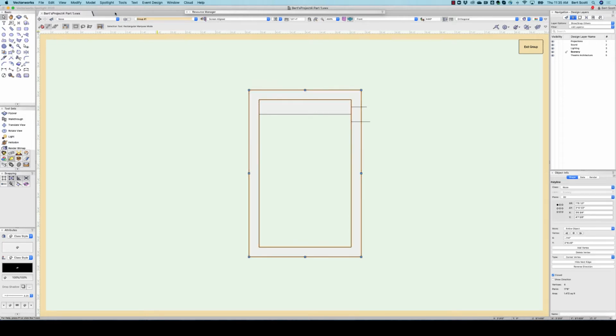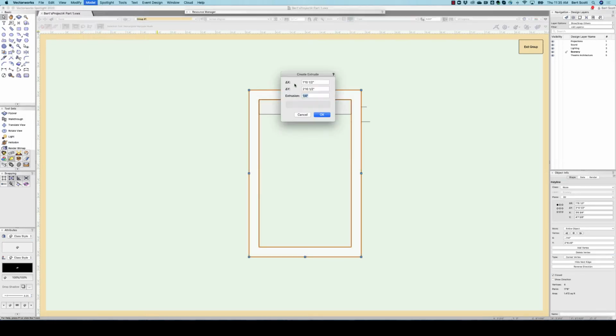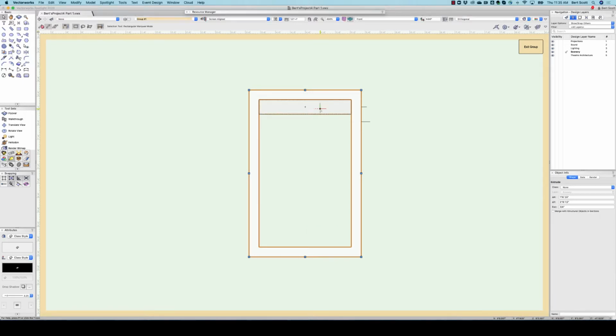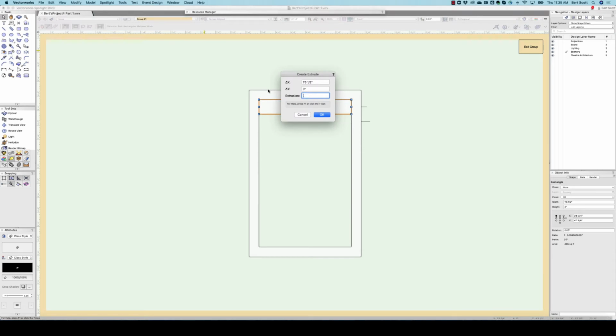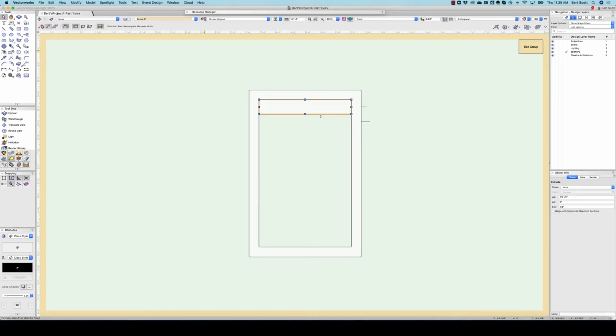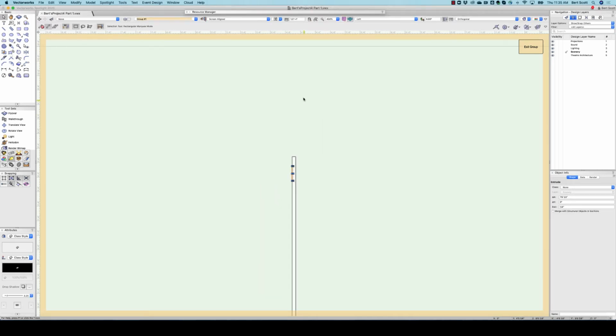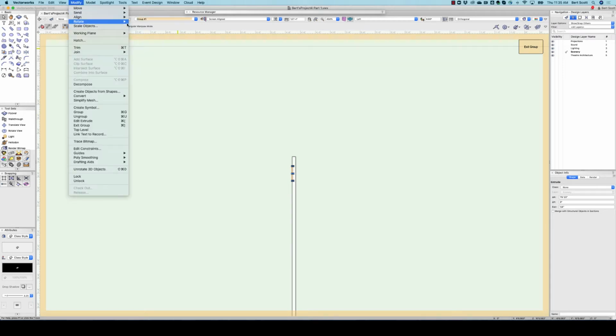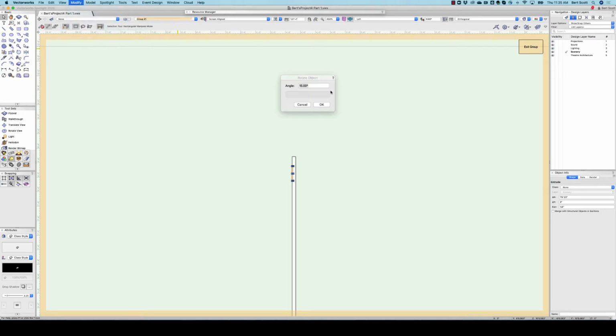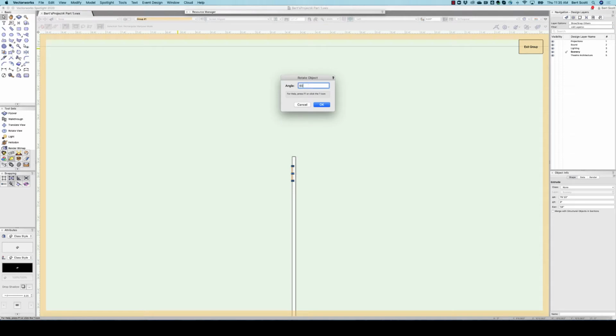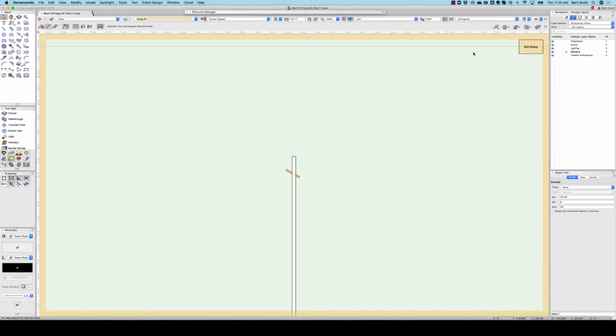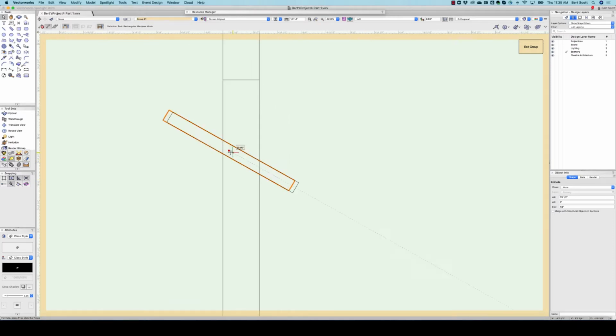Going to extrude our frame 3/4 of an inch. Extrude our blade 1/4 of an inch. Switch to left, rotate 60 degrees because we did 45 plus 15 last time. Go to wireframe, align the center of this with the center of the frame.